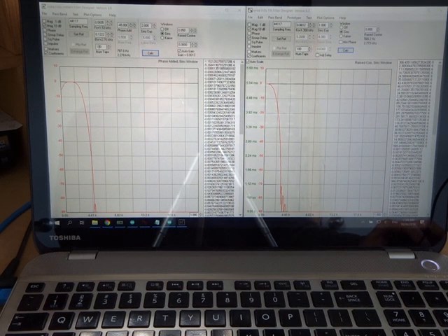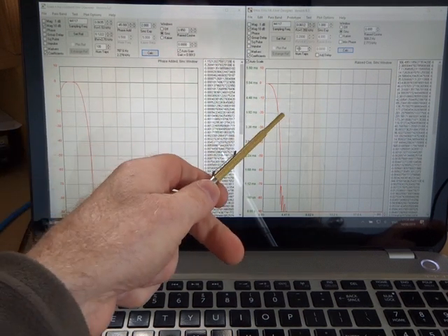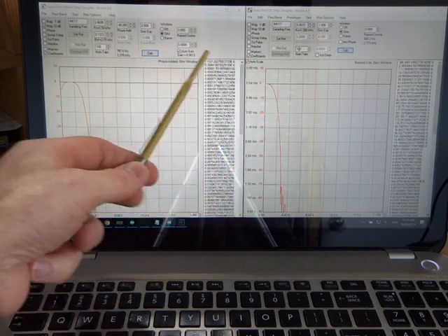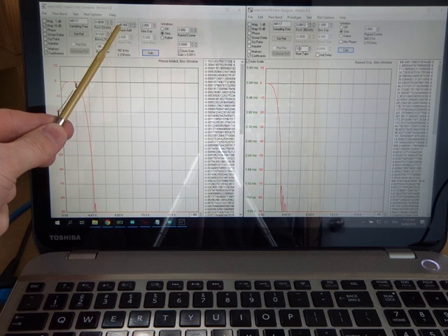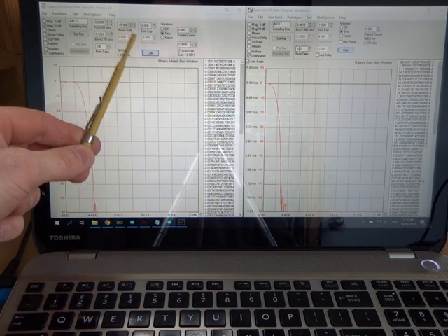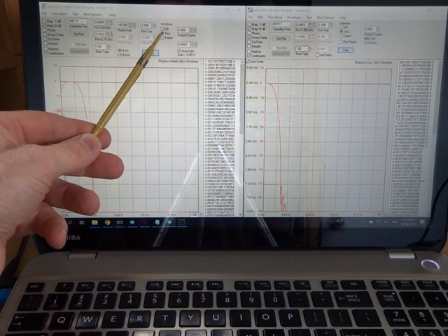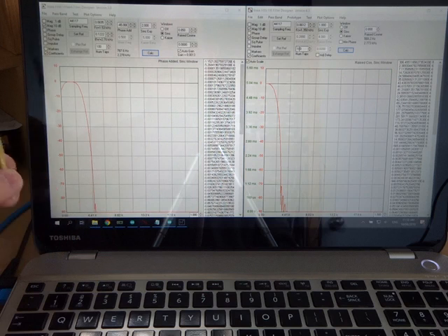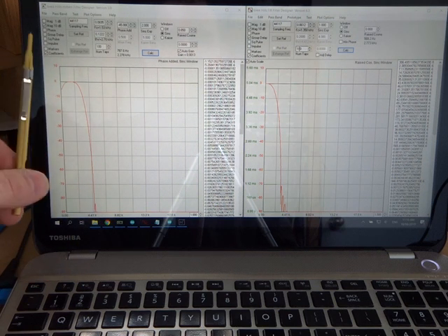I'm using 100 taps for both the Hilbert transform filters as well as the low pass filters in the Weaver technique. And then up here is our phase add. So at the moment it's on minus 45 degrees there, and if I make that plus 45, then the coefficients will be set up for the other phase shift. I've just optionally selected sync. Again, I haven't optimized any of these codes or any of these filters here. This is purely just an initial play around to see how it works.